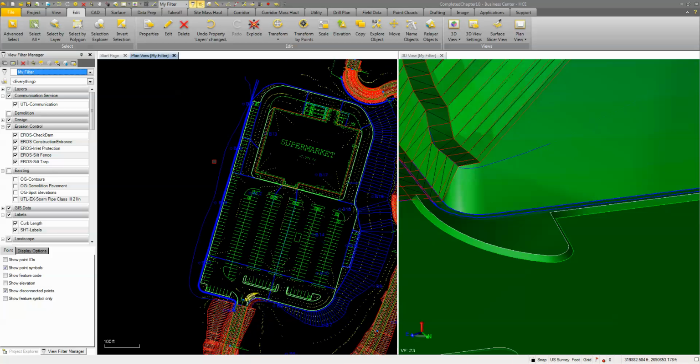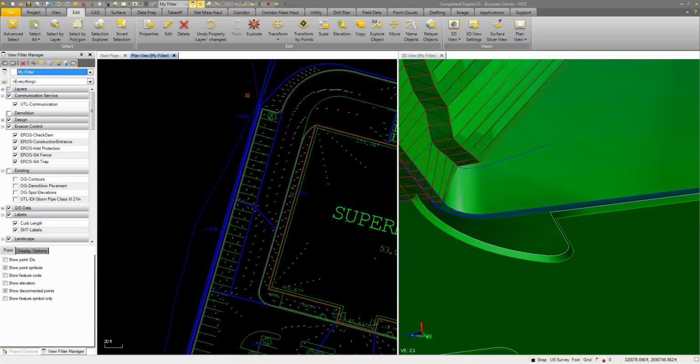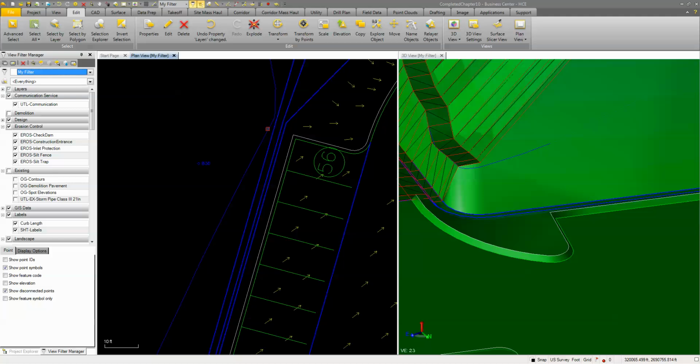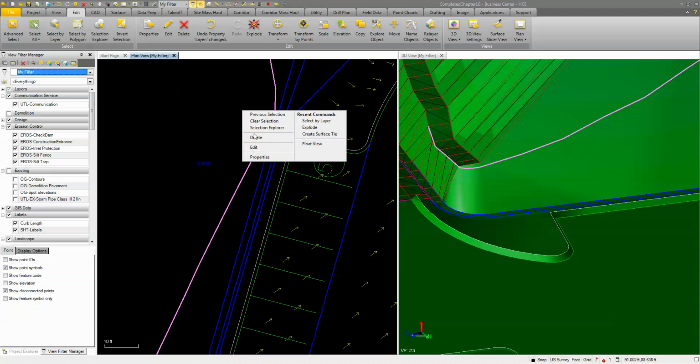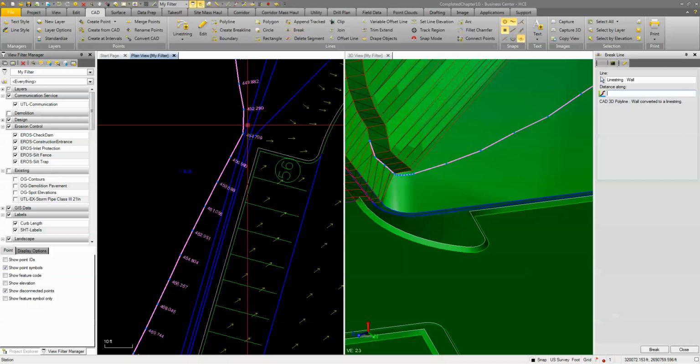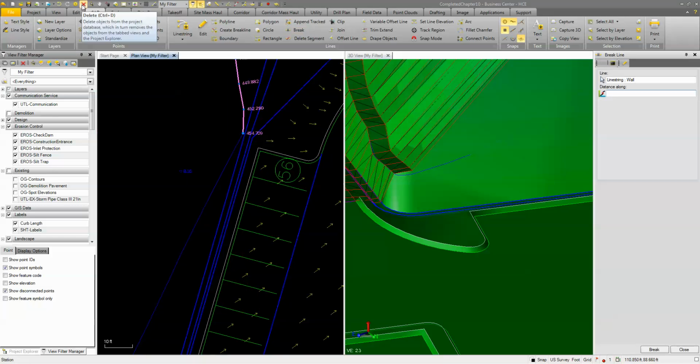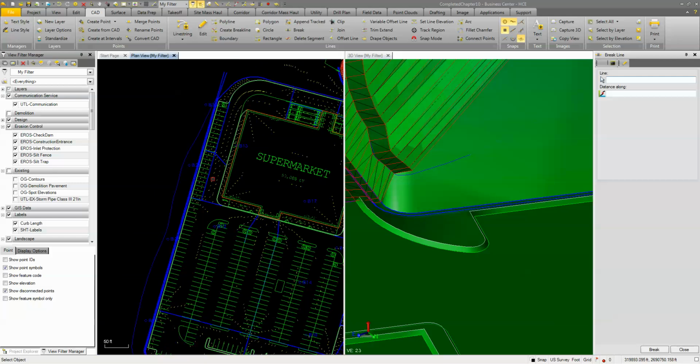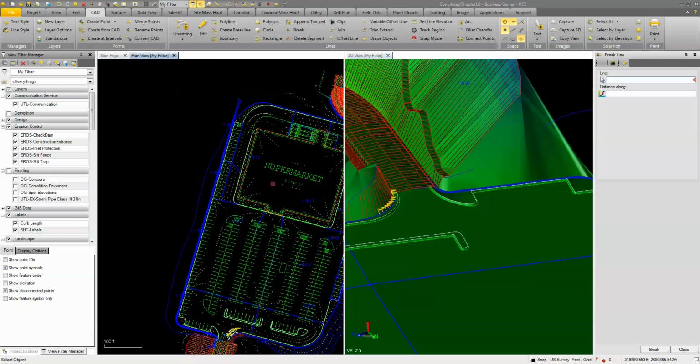So next, what I can do is come down here, and this is where that rock surface is, and that's where we go into fill basically. So I'm going to break this. Again, I'm just going to come up to my edit or CAD command or tab ribbon, and I'm going to go break, and I'm just going to break that off right there. I'm going to take this line and we'll go ahead and delete that piece. Right, so now I've just got that line there.